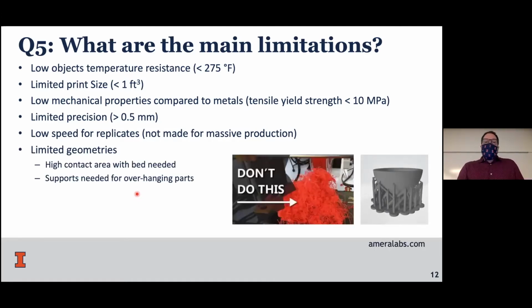And you are limited in geometries. That's, I would say, one of the big drawbacks. Let's say you want to print a sphere, like the Pokeball. If I install it on the bed, the area of contact with the bed is super, super small. When the extruder applies the plastic, it's going to create some sort of resistance, and then the part is going to unstick. You're going to end up with a big blob of lost material.